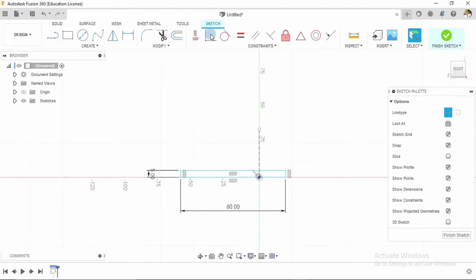It might look like obviously we are using more processes to do this. Yeah, for this we are using more processes, but then when we have our feature tree, we just have 1 and 2, which means that if we are to load it into a project or assembly workspace, it doesn't have to load the whole list of processes. That's one of the advantages of having few features here.